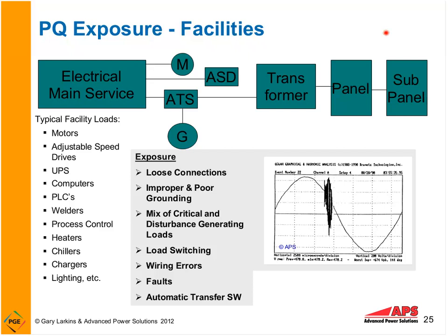Just to give you a quick example, we had one place where they were a robotics welding equipment manufacturer. And what they did is they installed these new robotic welding machines. So once they started operating these machines, all the small UPS systems in their office that was fed off the same power transformer started going to battery backup because they were creating sags when they started welding. The solution there was not a utility solution. It was actually a facility solution to put equipment on those robotic welding machines that would slow down the inrush of current to those machines, allow them to operate properly but not cause major sags.